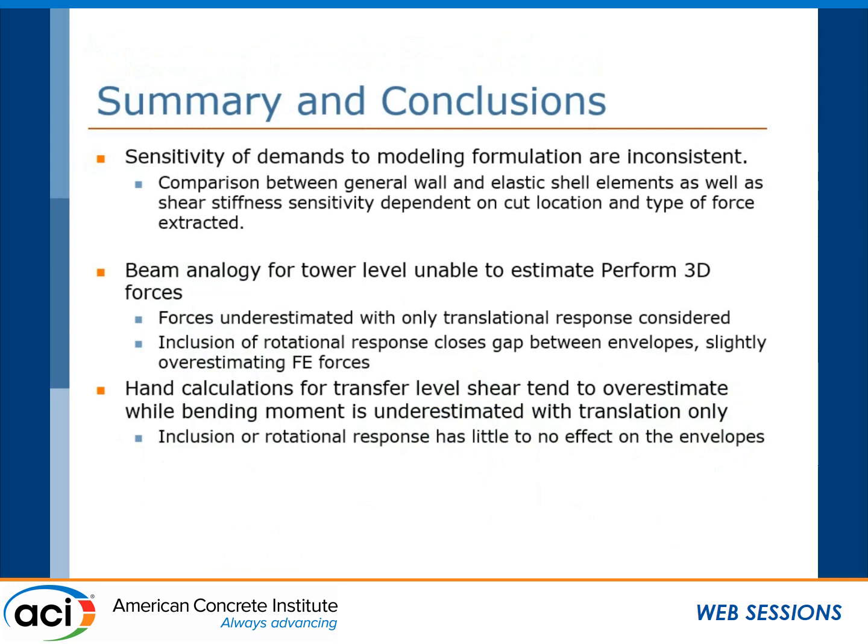So in summary, from this small study we did, the results we're getting from Perform 3D show there's not really much of a trend with modeling the diaphragm as nonlinear versus linear, and there's no real trend right now with the effective shear stiffness values that we're getting. As you saw from the slab shear, there were locations where a higher effective shear stiffness on the slab would result in a higher slab shear, but in other locations a higher shear stiffness would result in a lower slab shear.